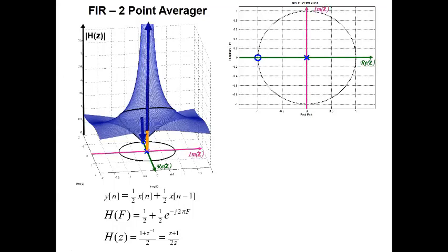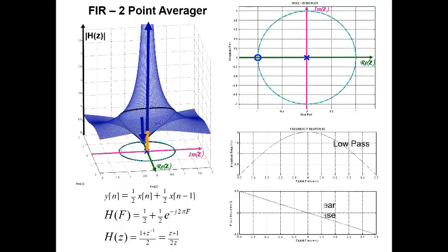All right, we can see that with our rubber sheet analogy as well. When we have the rubber sheet, a 0 here on the unit circle, that rubber sheet's pulled all the way down to 0, so we absolutely have to get the magnitude response that's pulled down. This pole in the middle is holding up the rubber sheet, pushing things up. And as we see, the combination of pushing things up in the middle and yanking them down over here is letting them rise up a bit on the other side. And that's giving rise to our low-pass filter kind of shape. One way to make a low-pass filter is push up the middle and pull down the high-frequency area here.